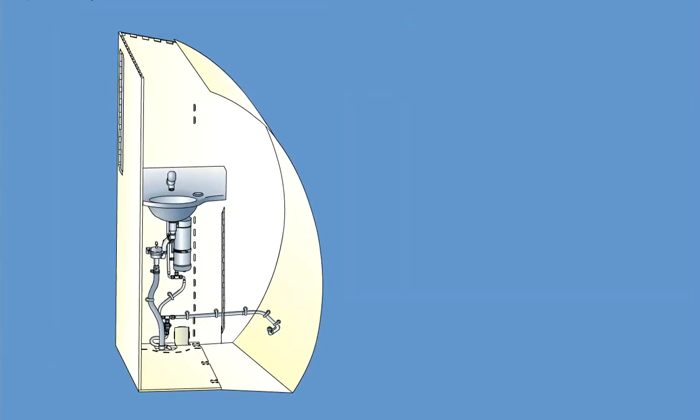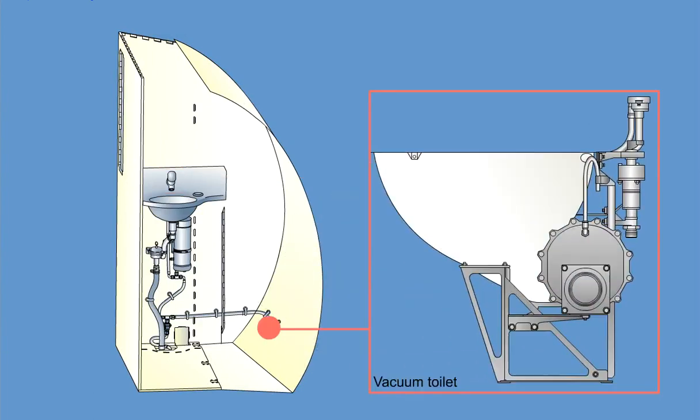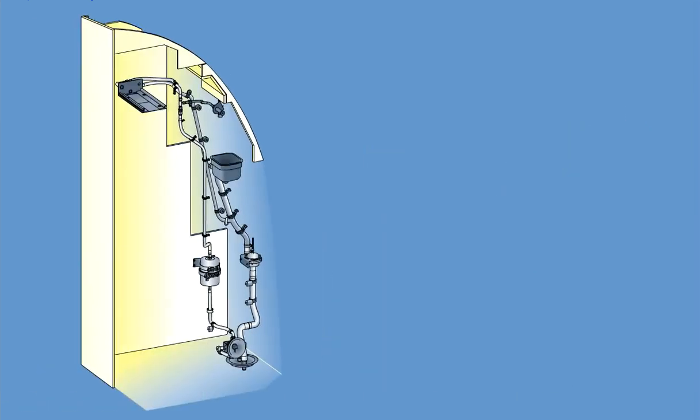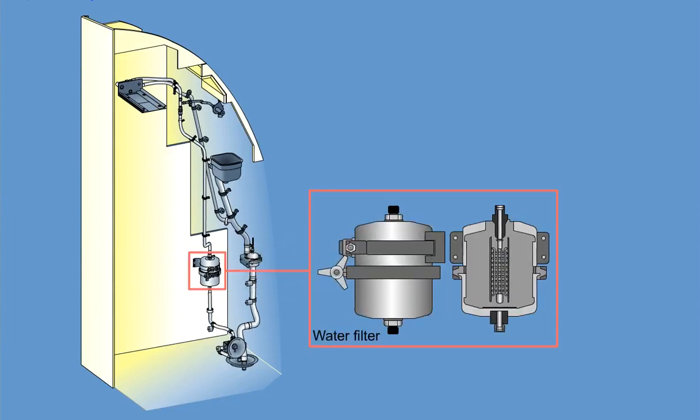Water is supplied to the sink by a wall-mounted faucet located above the sink basin. The potable water in the lavatories is also used on the rinse valve in the vacuum toilet assemblies for flushing. The supply lines to the wall-mounted spigot and the coffee maker rail assembly in the galleys contain a water filter.